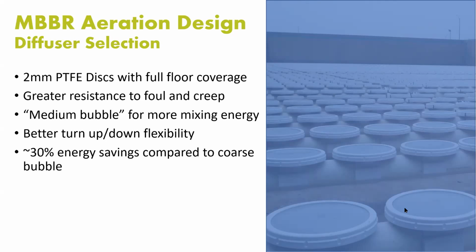We do not like to use tubes in MBBR systems. They simply create different patterns and the media interacts with them a little differently. It's not that they're bad to use in MBBR systems, but we simply prefer to use discs.